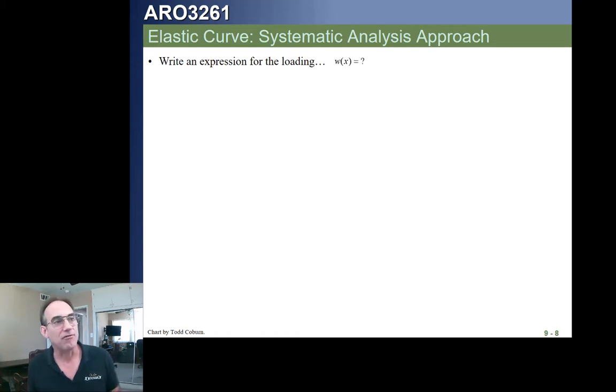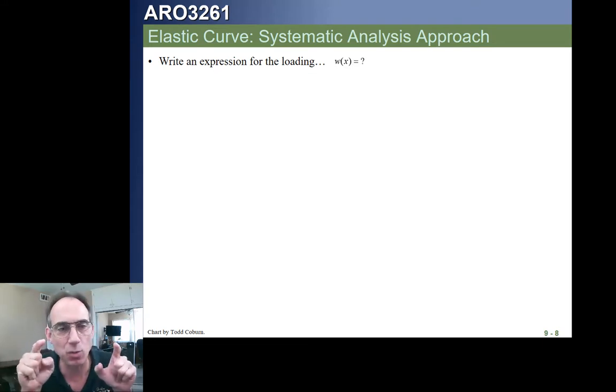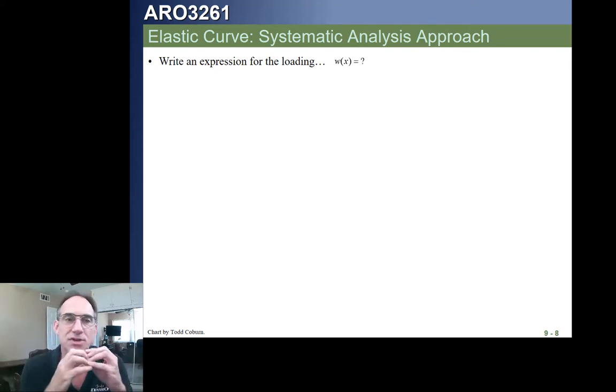So what's the first step? The first step, here's our systematic analysis approach. This is the key. We're going to write an expression for the loading. What's the easiest way to deal with beams with a loading that's not super simple? Singularity functions. Pull up your singularity function table.